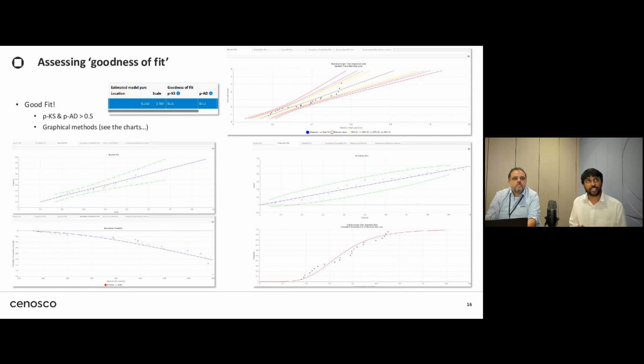So that was typically your first step, just what we highlighted earlier. The second step was to assess your wall thickness results and identify if the results were a good fit. Because if we were getting contrasting results with wall thickness results, maximum wall losses, then this goodness of fit would have highlighted such cases. For example, we have inspected 23 tubes. If about 5 tubes were corroding at a very high corrosion rate and the remaining 18 tubes at a much lower rate, that would have been evident in the goodness of fit data as well.